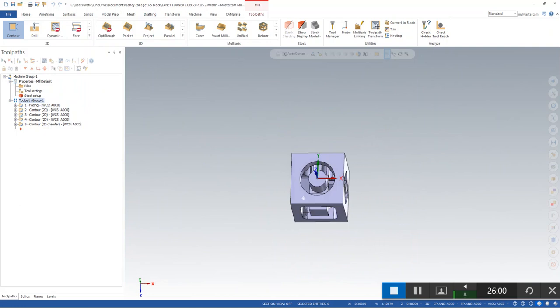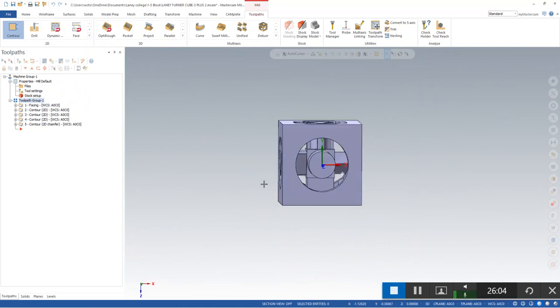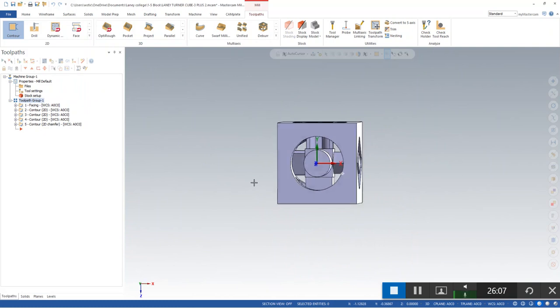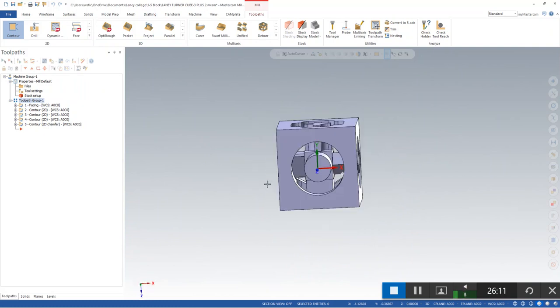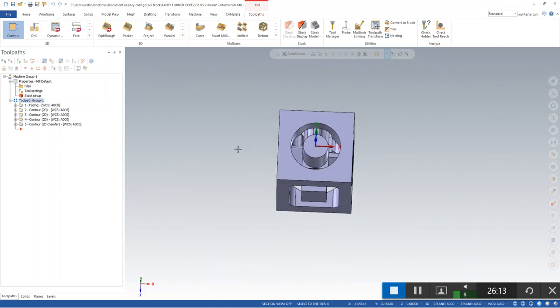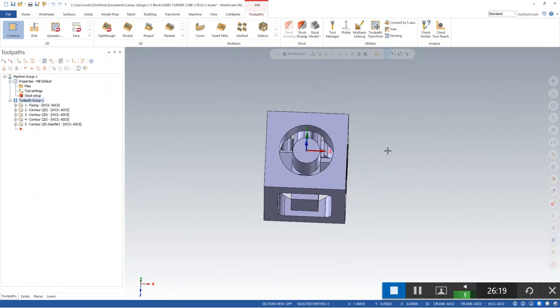So now at this point, you have to know what machine you're going to be running this on, so you know which way we're going to rotate when we move to the next face. For now, we will program it for the TRT, and later on I'll show you how we can switch it over to the UMC.